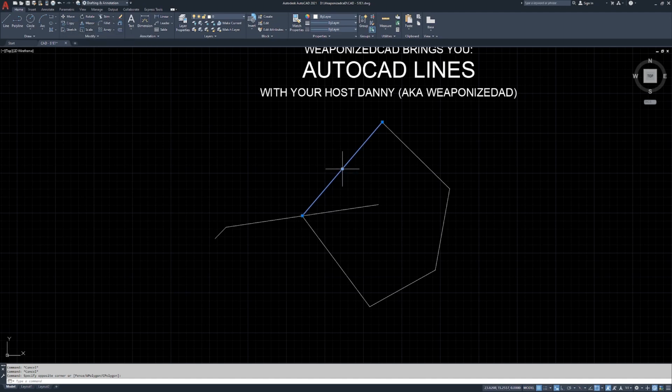So let's say we wanted to grab this line segment from the midpoint grip. Because it's a line segment, it's going to have a start, a middle, and an end. If we grab from the middle grip, it's going to move the entire object. If you're in the middle of this and you hit escape, it throws the line back where it was, because according to AutoCAD, you haven't actually dropped it anywhere new.